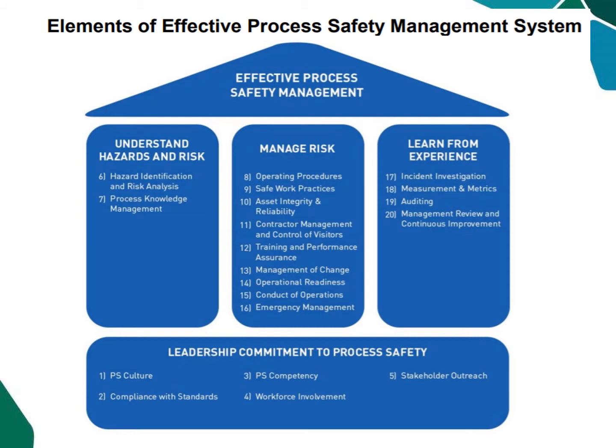Namely, the main categories are understanding the hazards and risks with the materials we're using, how we can manage those risks, how we can learn from experience from prior incidents or incidents at other facilities. And then we also have to have a leadership commitment to process safety. Our leadership needs to be present and also provide the resources necessary to have an effective PSM program.